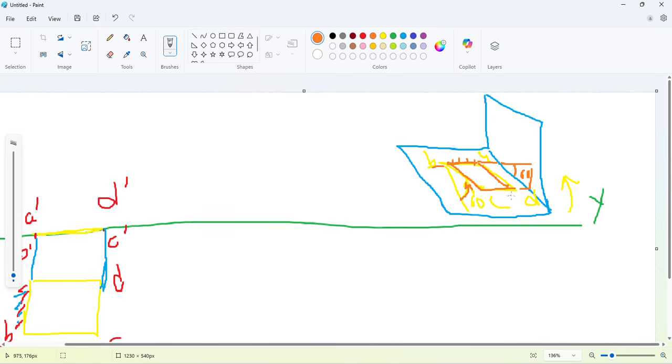again we will have a rectangle, but in comparison to the previous one, this length will be here. Suppose this is 30 mm. So when the surface is inclined at 60 degree, this rectangular surface is going to be a little less in length. It is going to be reduced lengthwise. You can observe this in this picture here, or you can imagine this. If this surface is inclined at an angle, the resulting top view is going to be a compressed one.